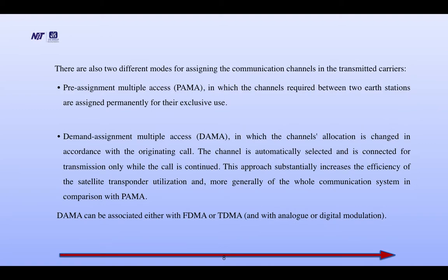There are also two different modes for assigning the communication channels in the transmitted carriers. Pre-assignment multiple access, PAMA, in which the channels required between two earth stations are assigned permanently for their exclusive use. Demand assigned multiple access, DAMA, in which the channel allocation is changed in accordance with the originating call.